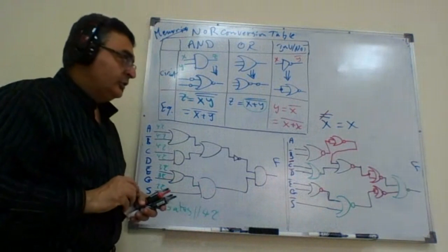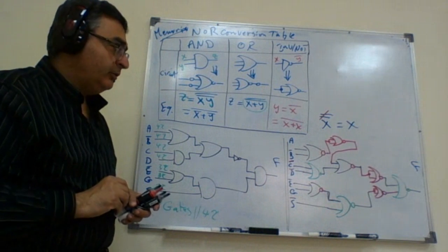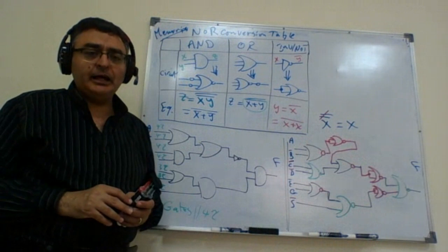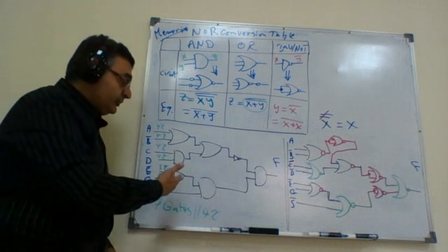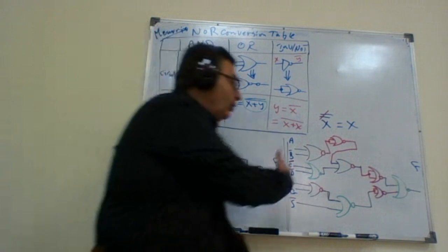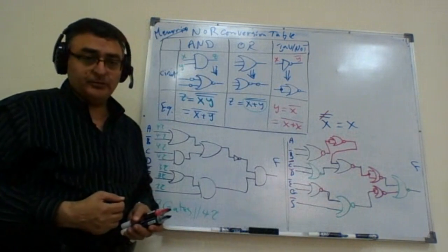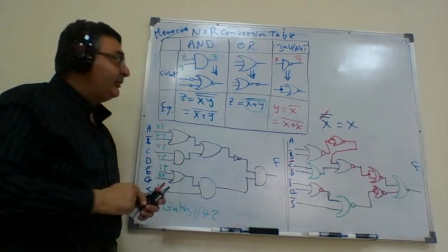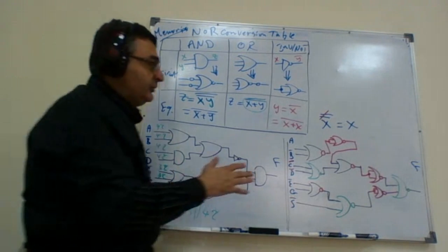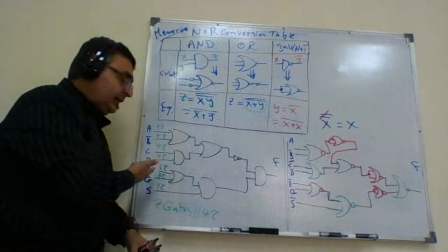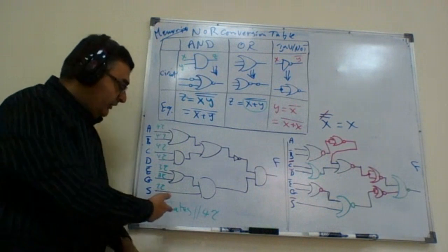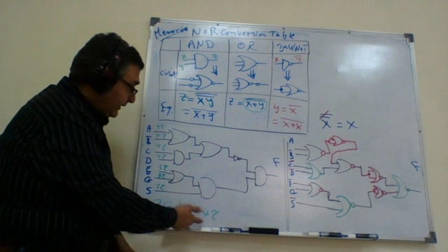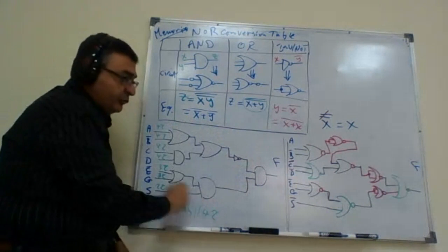So the circuit now, if you look at the circuit, you will find no other logic gates other than the NORs. So I converted the AND, OR, inverter circuit to an all NOR implemented circuit. Now the question, why do we call it multi-level NOR? Because the circuit that we have achieved here, originally the circuit was not 2 level. It was actually 4 level or 4 tau delay. The propagation delay from the inputs to the outputs is 4 tau.